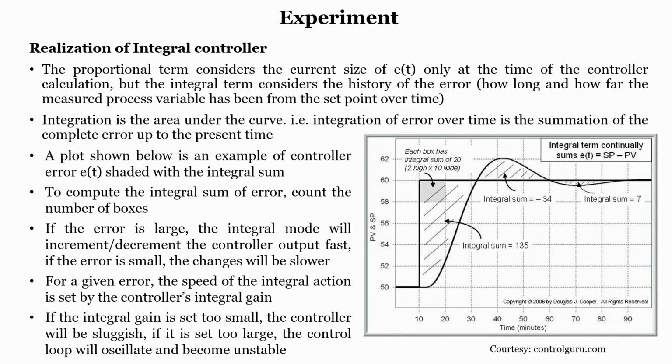So, as we have already seen in the theoretical explanation by the professor, so just recall. So, if I say this is my set point and this is how the output keeps on changing, right. When you do an integration, what it does is that it adds up the error factor. So, the dashed line is nothing but the error output, right. So, it adds up at this particular point what is the error that I have. So, that sum is 135.